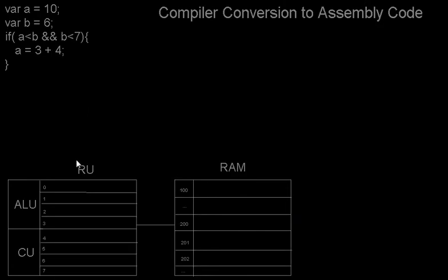When we're looking at this, we'll also consider this is our CPU, so we have our control unit. We'll be basically doing that job ourselves manually. The arithmetic logic unit will be doing that job. The register unit contains registers, so we have 8 registers, and we'll track what's going in there, and the memory system. We'll only be concerned with a couple of addresses in here. We'll say that the value A will always use the address 100, and the value B will always use the address 200. This would be determined by the operating system when the program is running. So we'll make those choices now.